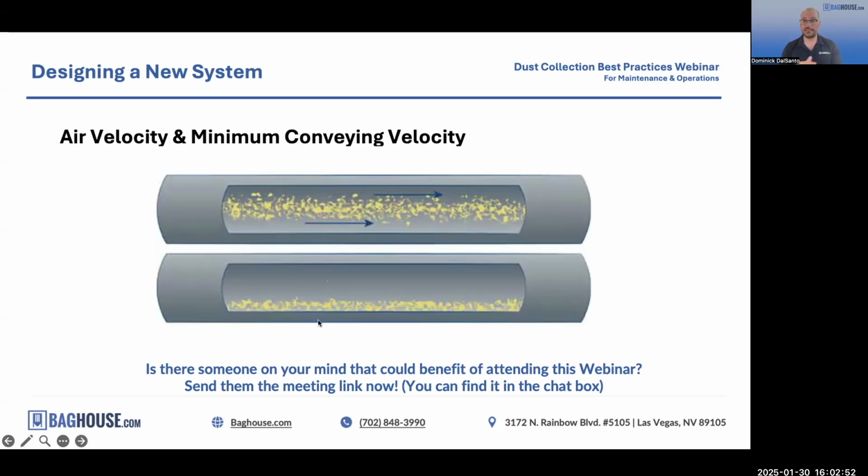If you go lower than that at any time, what happens is what you see in the picture, where the dust builds up in the bottom of the pipe, and then you get all kinds of other knock-off problems. You get restriction, because now the pipe is smaller inside, so it actually speeds up the air, causing abrasion after it. You also get more resistance, so it lowers the airflow through the whole system, and it plugs it up.